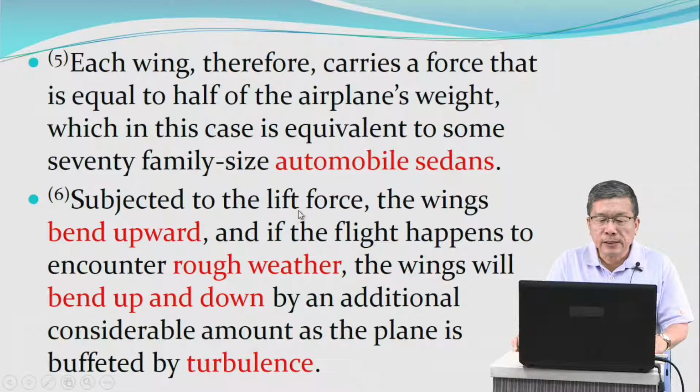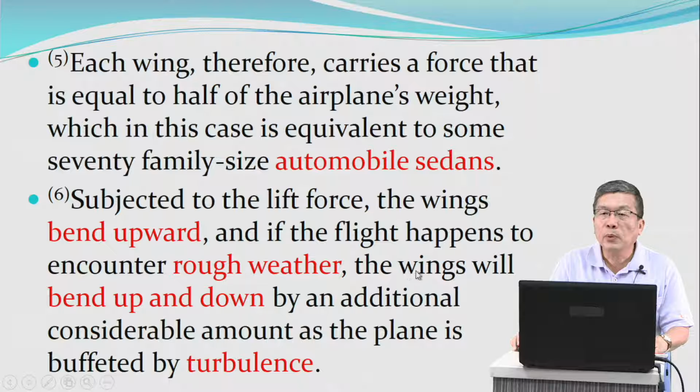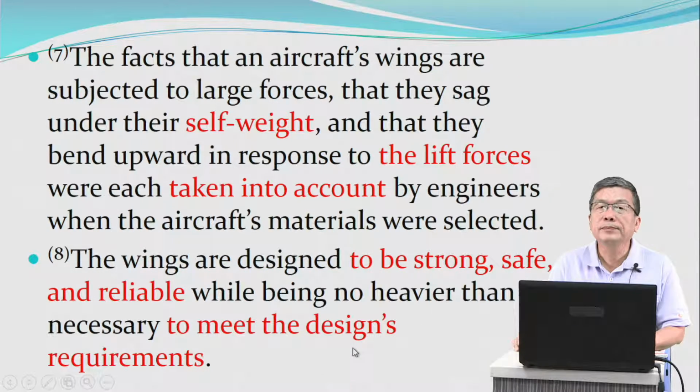Subject to the lift force, the wing bends upward, and if the flight happens to encounter rough weather, the wings will bend up and down by an additional considerable amount as the plane is buffeted by turbulence.